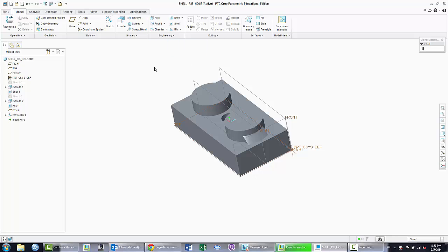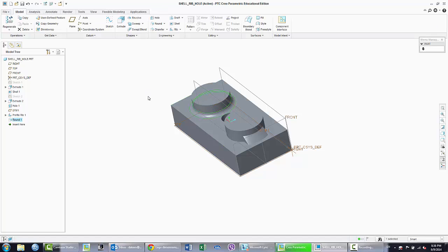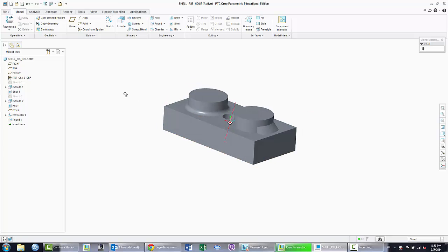We can see that we have already used 3D tools such as rib, hole, and shell. And in previous video we have already learned how to use round. In order to add round, we will simply click round and then define the corner. Let it be 0.5, for example. And once I click OK, my round will be added there. I hope this helps, and see you later.